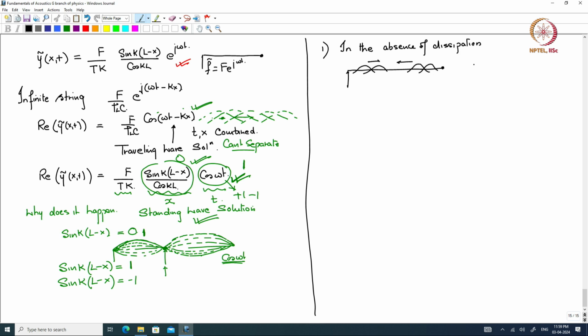That is what we saw, the magnitude of B was equal to the magnitude of A. They may be phased differently, does not matter, but the magnitude of B, the returning wave, is the same as the magnitude of the forward travelling wave. That is the reason that you have an interference between equal amplitude waves that leads to a standing wave.